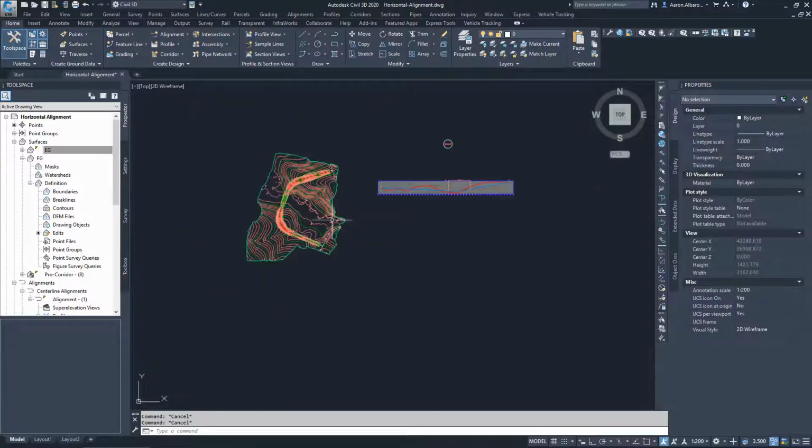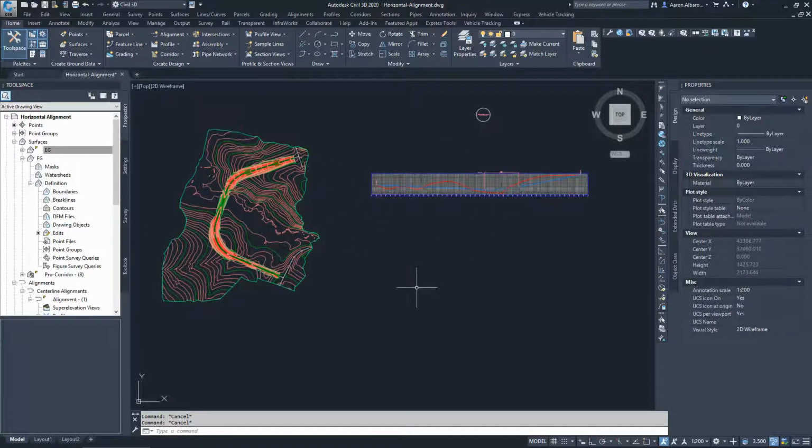At this point we finished kind of modeling for our road, guys. We created our alignment based on the requirements we had from the client. We created our existing profile based on the location of that alignment. We created the blue line, which is the proposed profile, what we think would be better for the location of that road as a preliminary judgment, or design, for that road.